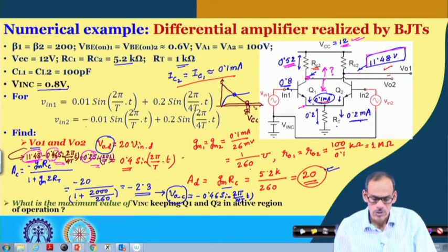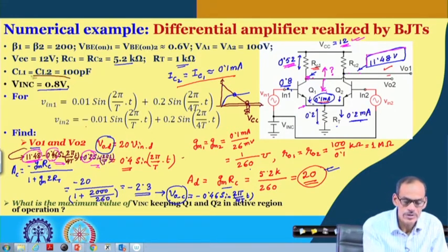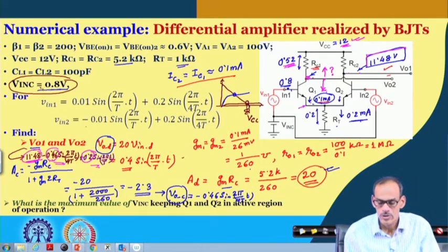Okay. So, this indicates that this voltage is probably quite low, alarmingly low, and the gain here is very small, particularly the value of gm is small, and that is coming from the device being almost, I should say, towards the cutoff.